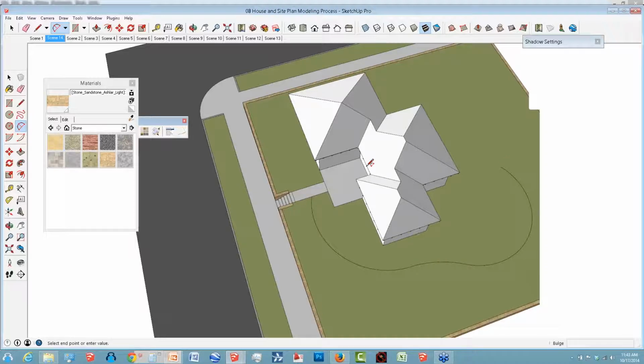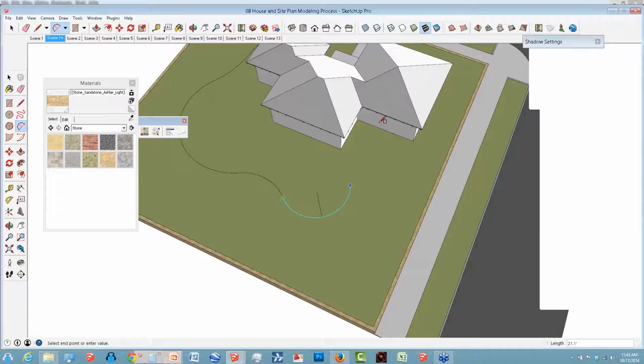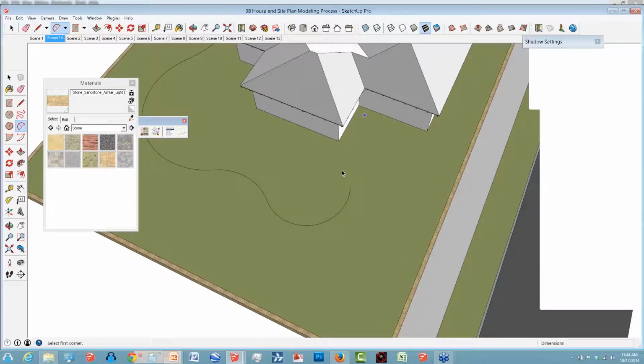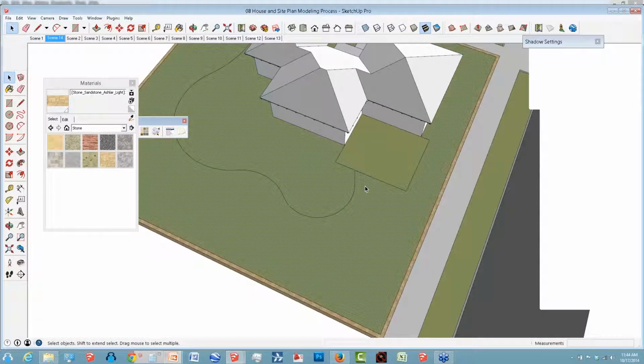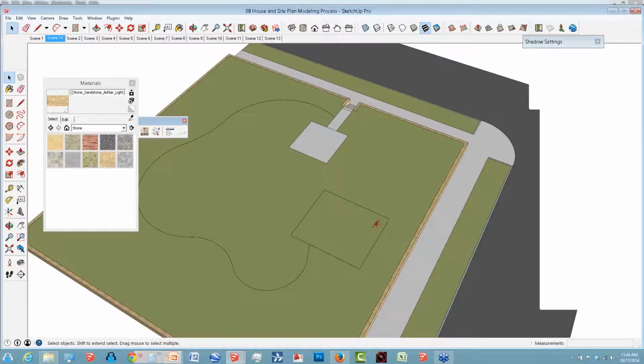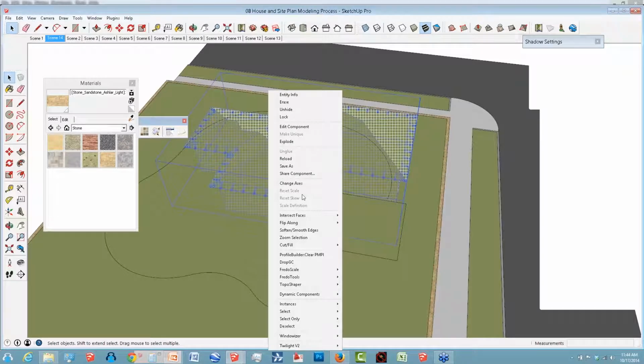You know, again, for a lot of people, and just to emphasize this point, what you're going to end up doing is really using your CAD drawing to leverage what you want to do here to create many of your site plans. And that's not a difficult thing to do. It is learning some of the nuances on how SketchUp works. So for example, right there, what I ended up doing was hiding the house. So, you know, just a little bit more of a basic tooltip there. You can hide and unhide objects in SketchUp, and that makes it easier for you to start working in it.